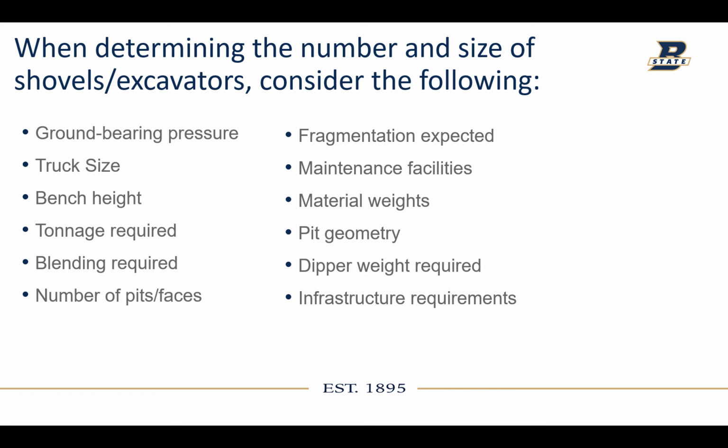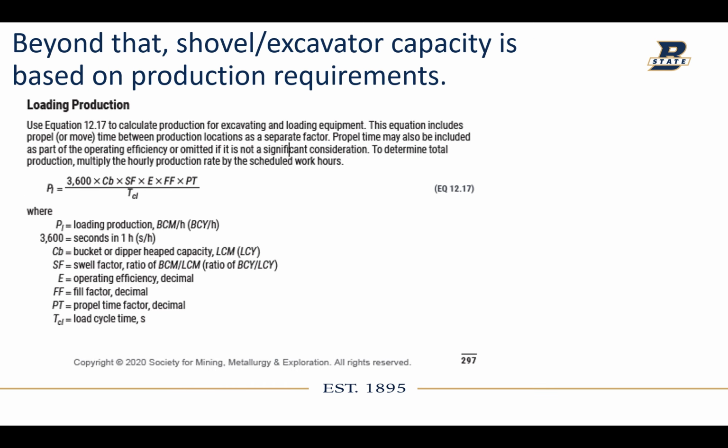You have to take all of this into account and design it based on production requirements, right? So you can design your shovel based on the production requirements. Like I said, it does still have to fit in the space that you're working. It has to load the proper size trucks that can run on the roads that you have.